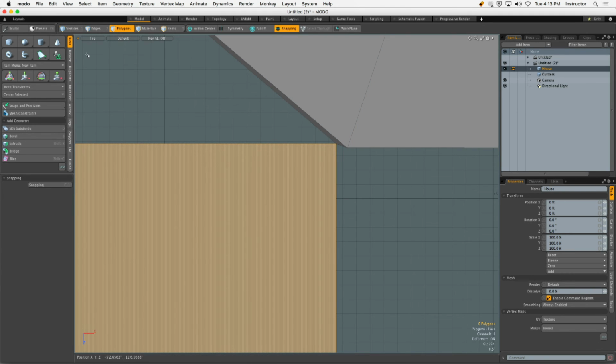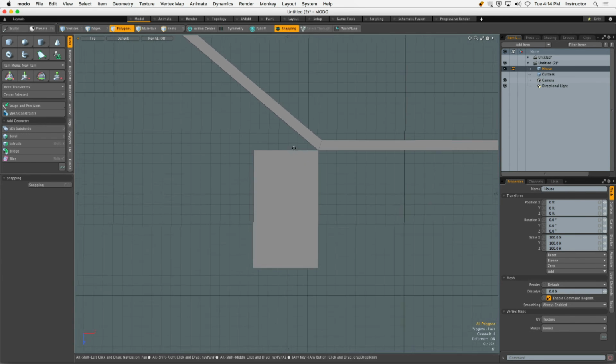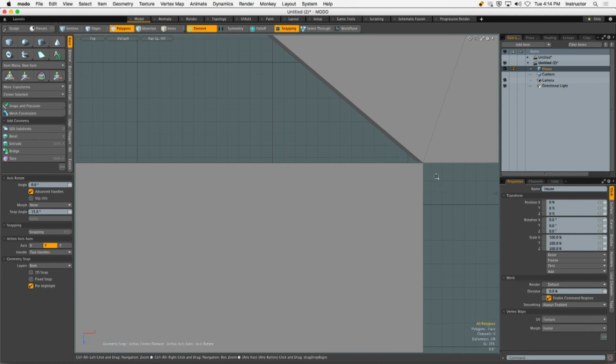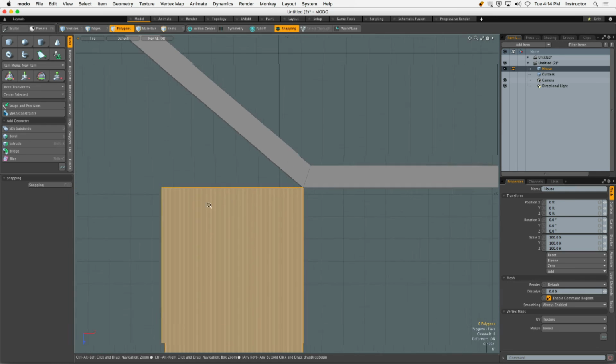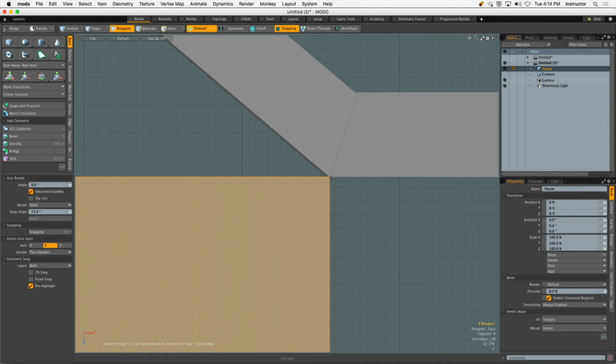I want to get the corner of my cube, right? So I want to use this angle here to help me figure out the rotation angle of that object down there. All right, now that they're in position, Drag, Snap, Planar Rotate, Snap Axis is going to be our guy. And I've got to apologize, I'm going to drop my tool. I forgot to select my future door. Let's run it again. Now, where we click is going to represent the area that we're going to be rotating around. So this is like the hinge.